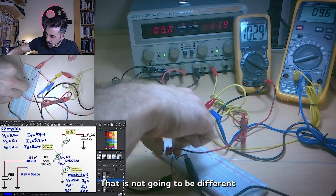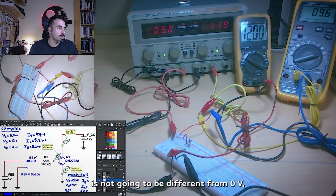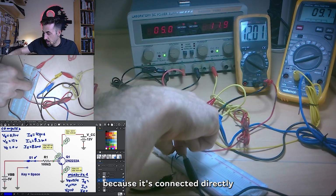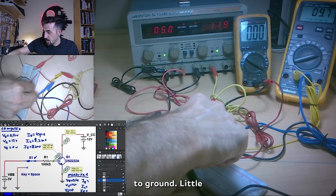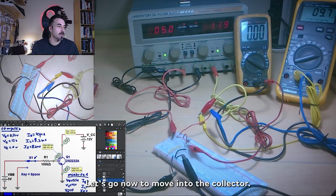That is not going to be different from 12, so 12 volts, no problem. Also the emitter is not going to be different from 0 volt because it's connected directly to ground. So also 0 volt, that is everything correct. Let's go now to move into the collector current.